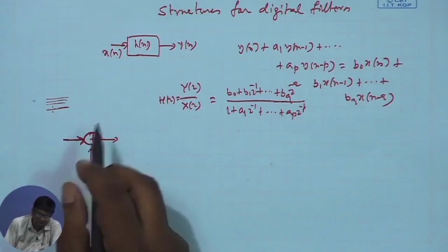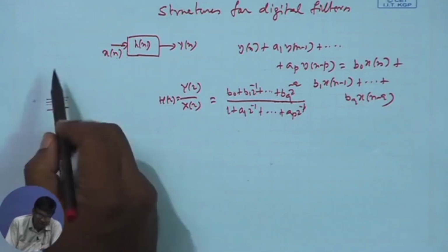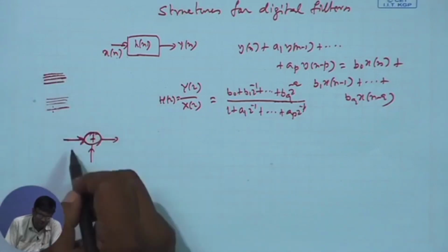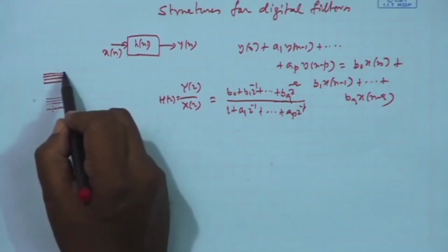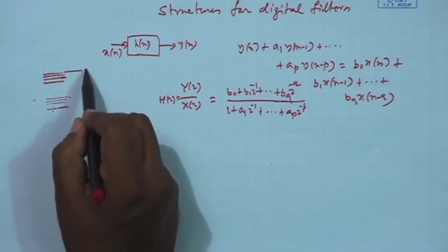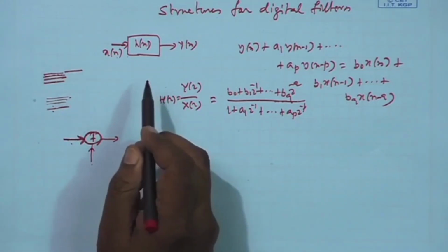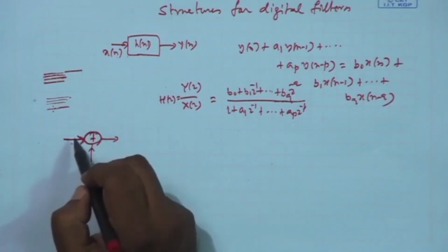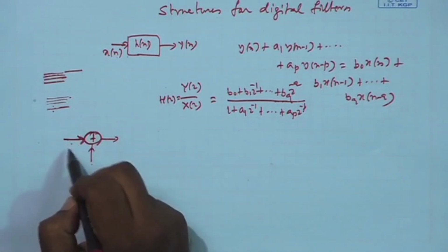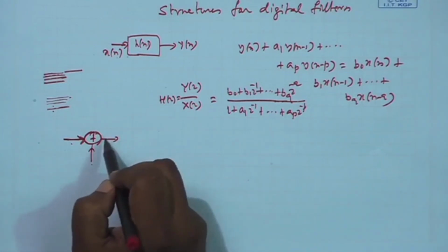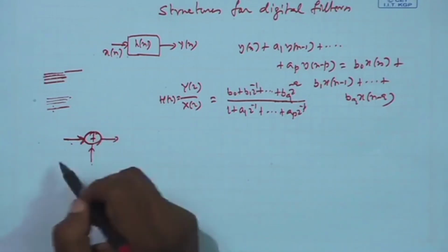This is a bus. So, this adder means if there is one set of bit lines for one data, another set of bit lines for another data, then you do addition of the LSB of this with this, then take the result out, then take the carry out, and then add the next to LSB of that with the carry coming from the previous addition, then generate a new result, and propagate the new carry again, like that.